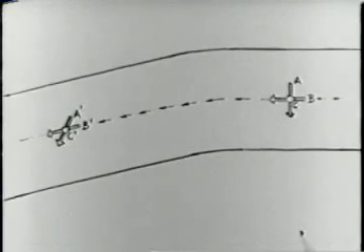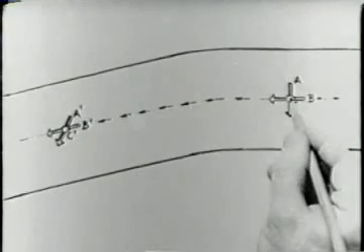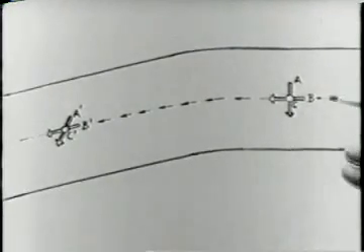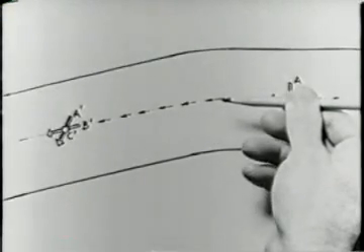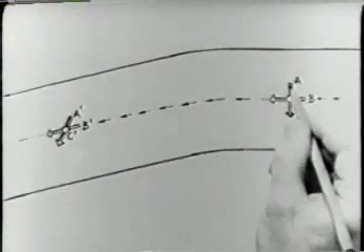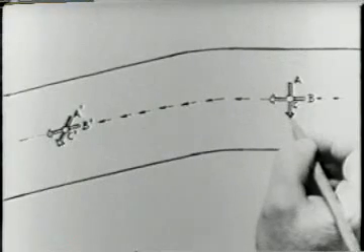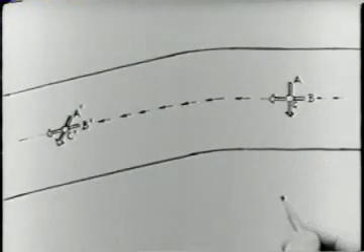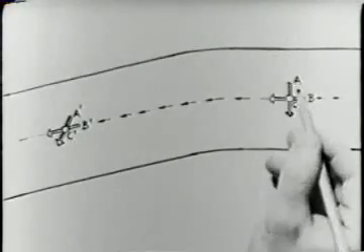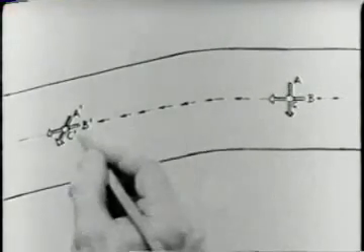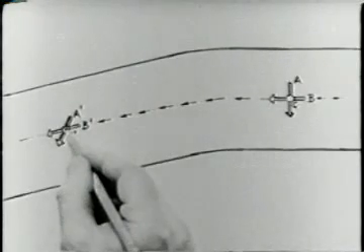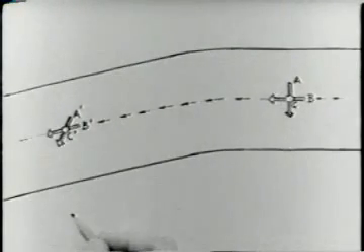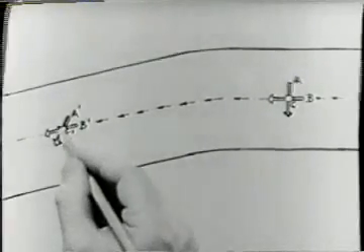Notice, though, that there is no vertical component of vorticity C nor any streamwise component of vorticity B. There is only a transverse component of vorticity A, associated with the viscous boundary layer on the floor of the channel. Now line C moves along the center streamline to position C prime, so there is no vertical component of vorticity, C prime.